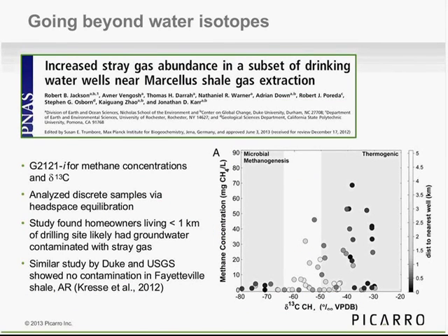And then finally, of course, as hydrologists, you're not only interested in the water itself, you're also interested in dissolved gases, in nitrates, many different nutrients, and so on. This is one example that has come out of Rob Jackson's lab at Duke University. It wasn't all done by cavity ringdown. It was also some conventional IRMS techniques, but it's just showing what else you can do. What they were measuring was dissolved gas in drinking water wells, dissolved methane, propane, and ethane in drinking water wells close to drilling sites on the Marcellus Shale.